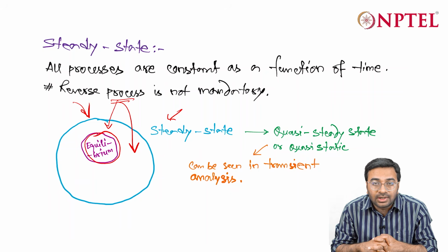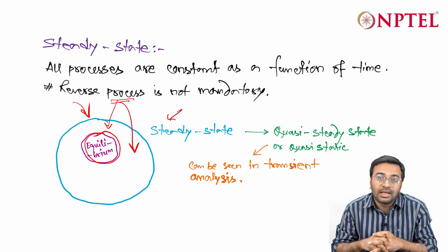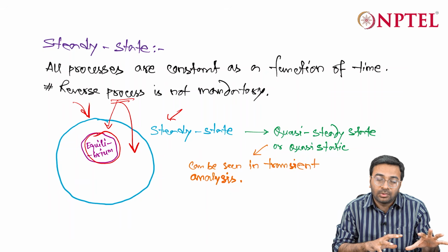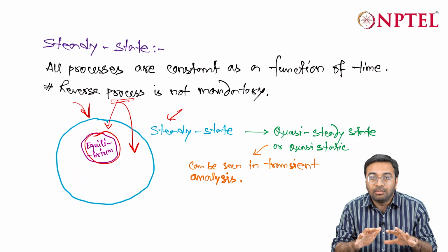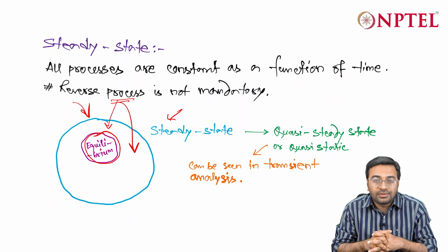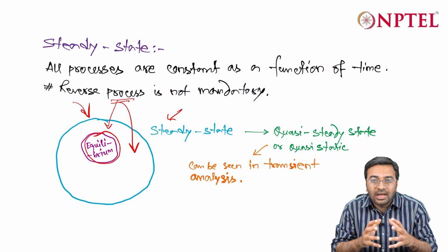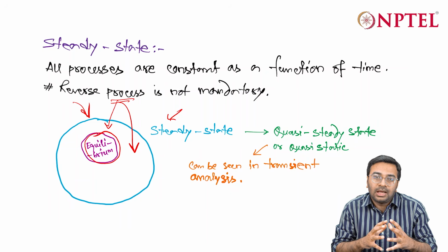We also have seen what equilibrium is, how equilibrium can help us to solve certain sorts of problems, and why we should consider equilibrium as the initial starting point of a certain problem. We also have seen what steady state is, and how steady state is related to equilibrium or how they are different. So after all this discussion, we now have a comprehensive idea about carrier concentration. We now have some understanding about equilibrium and steady state.